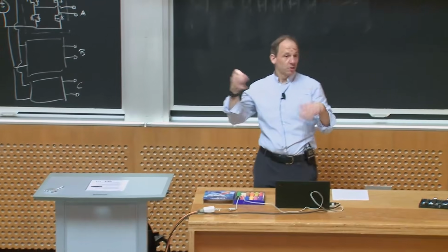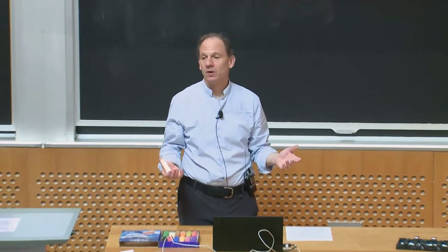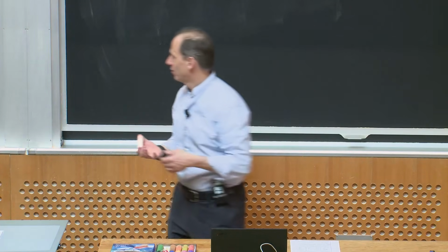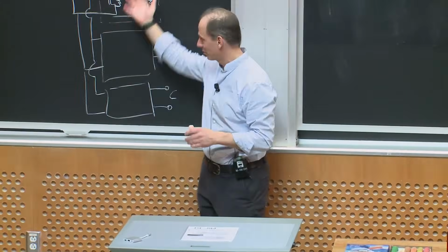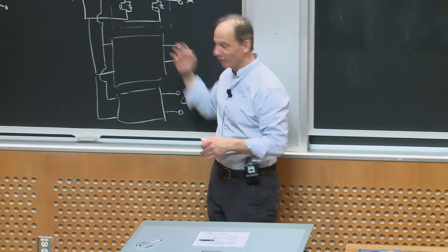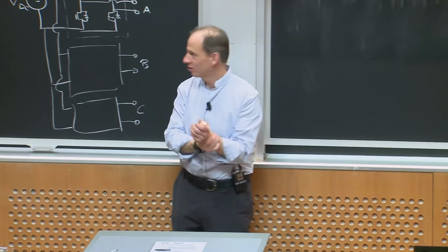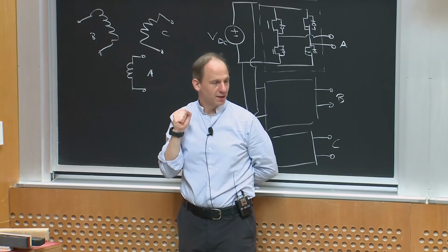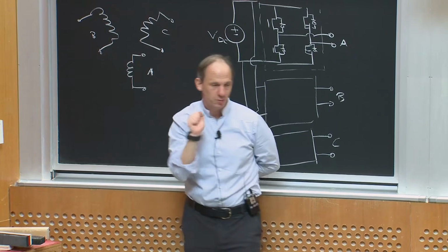And in fact, sometimes people do this. Okay, and in fact, actually at MIT right now, we're building a megawatt system that basically has this structure. It's sets of single-phase inverters that drive a three-phase system where the machine is a custom machine and has so-called open-ended windings like this. Okay, so it works perfectly well.